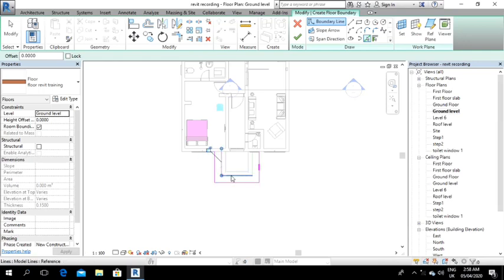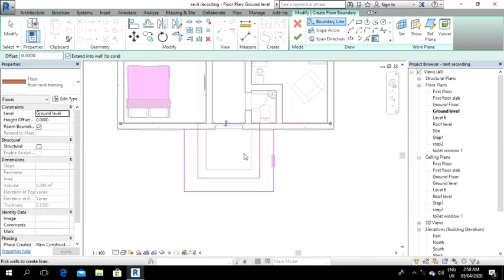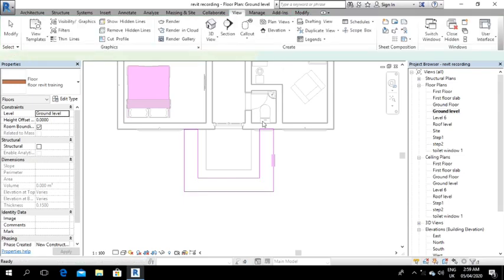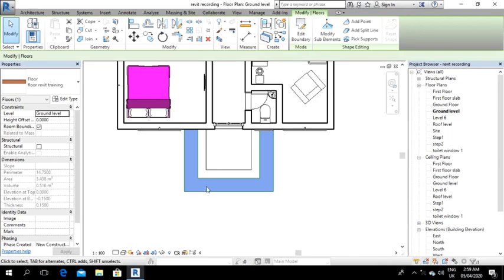Okay, now use your pick line marker and select this floor. Do the same for these lines. Then you can pick a wall like this wall to make an end. Move it towards this side, outside. Then use your trim to create a perfect loop. Okay, I'll use line to complete this one. Okay, so our floor is set. Click OK and it gets set.